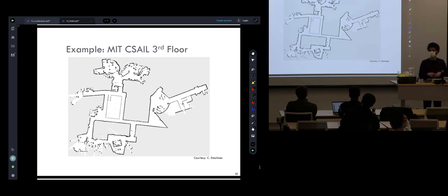Now, if you have this map, you can actually later load this map and run a particle filter in it. That's what we talked about in the localization lecture. Your likelihood will be different, right? You do ray tracing to get a range, and then you have an actual range for each beam. You get the innovation, and then update the weights. So this covers the other side, which is the mapping part.